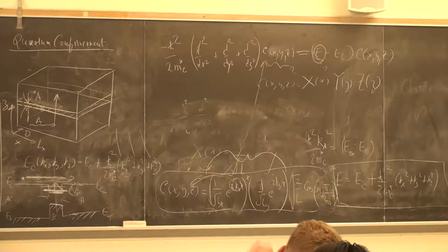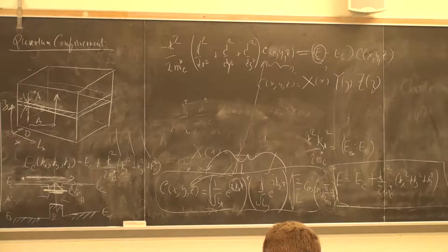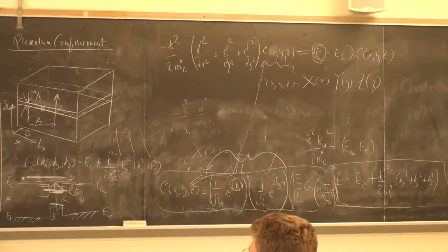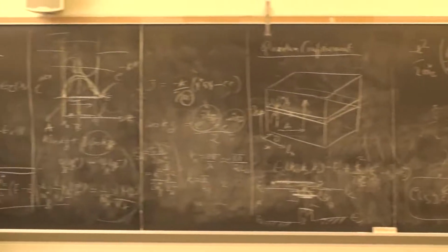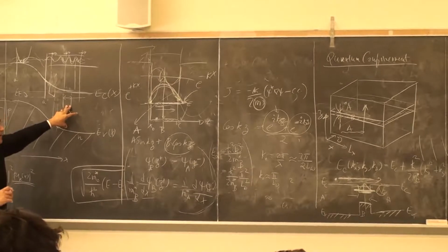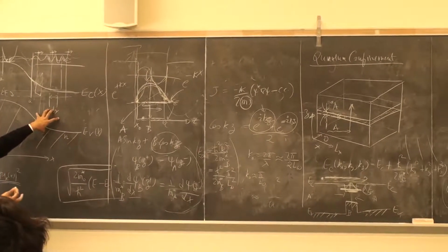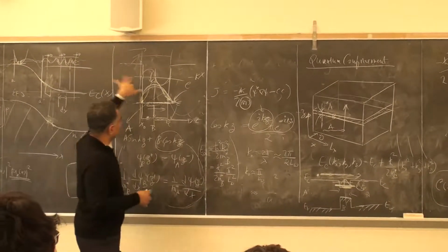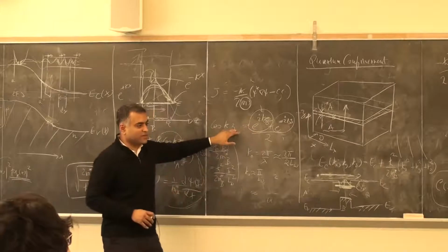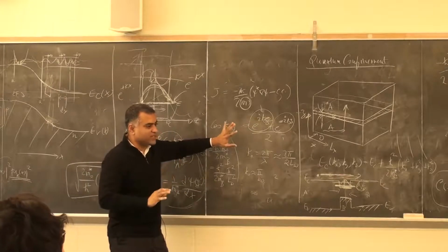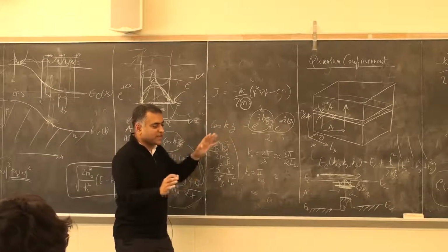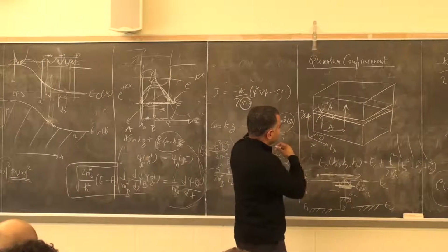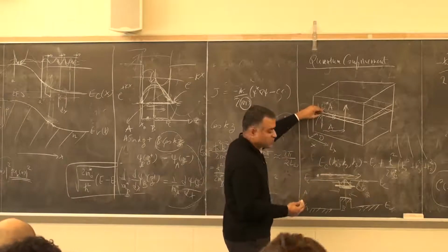Exactly right. Good point. If you look at what the effective mass theorem is doing, it first said that if your electrons are moving in a crystal, it's exactly the same as a free electron, except its mass is different. If you put a donor atom, it's the same as a hydrogen atom, except mass is different, dielectric constant is different. Now what it's saying is, if it's moving in a heterostructure, it's exactly the same as a particle in a box problem, with just minor tweaks to what is k, which directions it can move in. But the heart of the problem, you have mapped the problem of a semiconductor in a quantized heterostructure to a particle in a box problem.